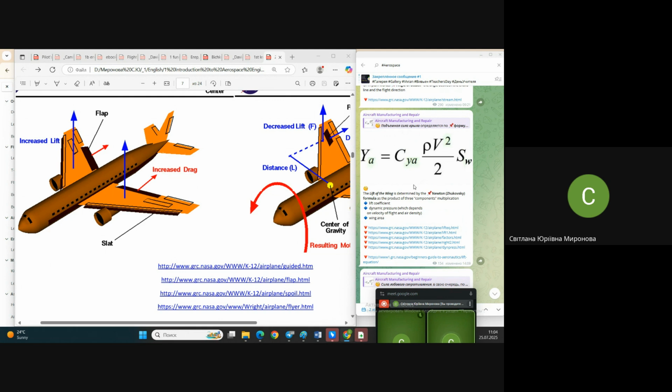That is why we move down and out flaps and slats much more significantly, in order to have both lift and drag. Why we need increased lift during gliding, I already tried to explain. We need to provide safe gliding, safe descending with significant reducing of speed.